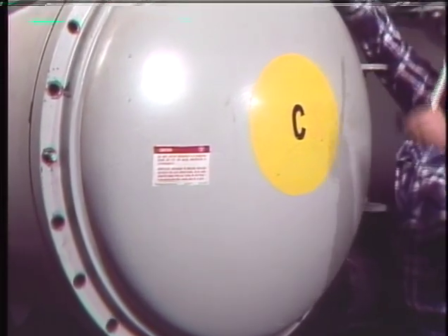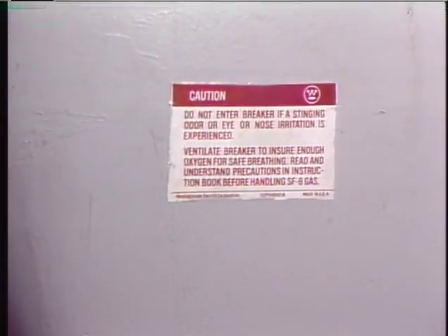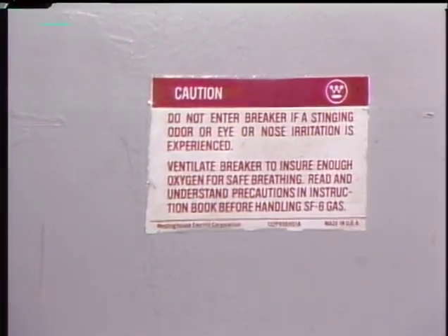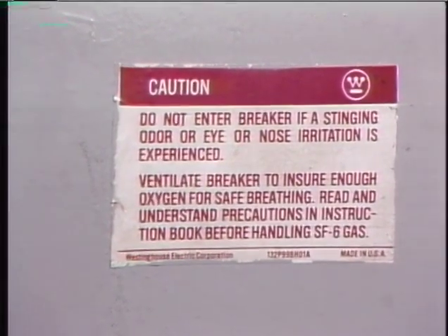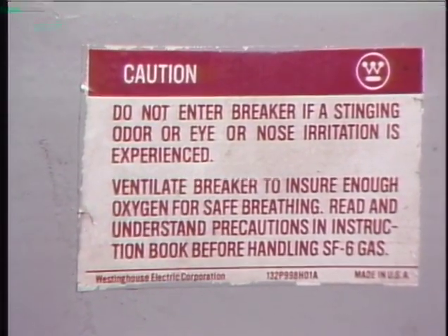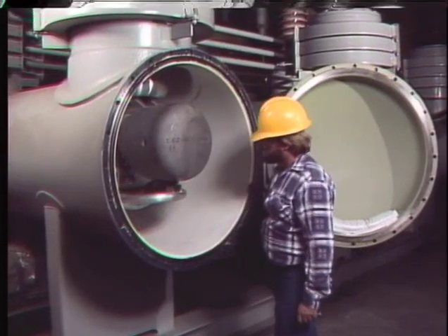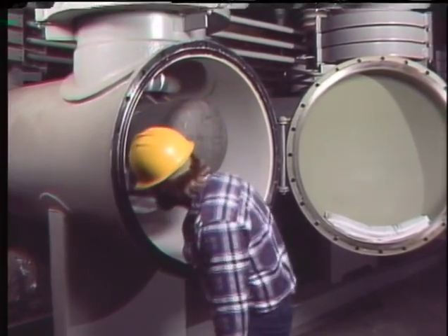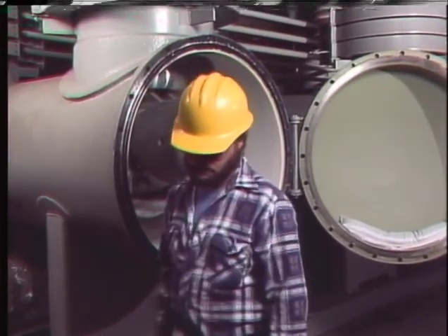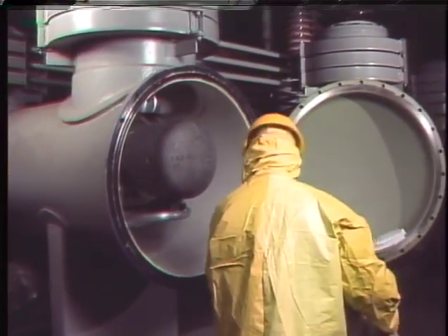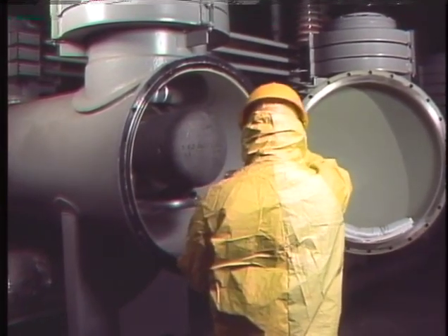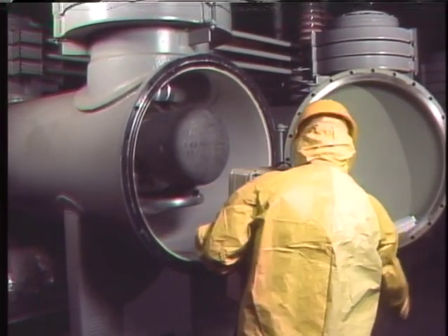A little caution should be taken when opening the doors. SF6 gas in its pure form is colorless, odorless, tasteless, and non-toxic. However, when arcing occurs in SF6 gas, a toxic metallic powder byproduct is formed. Gas containing this powder will have a pungent odor and is irritating to the lungs and eyes. If odor and irritation are noticeable when the breaker is opened, leave the area until it can be ventilated. Until the breaker is ventilated and cleaned, a mask should be worn so that you don't inhale the toxic powder. Protective gloves and clothing should also be worn to prevent skin irritation.